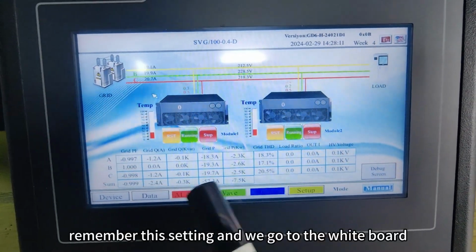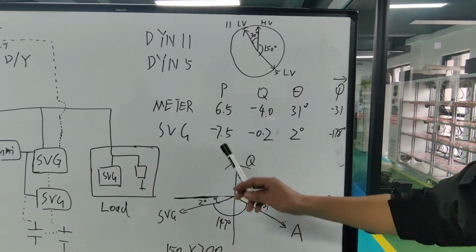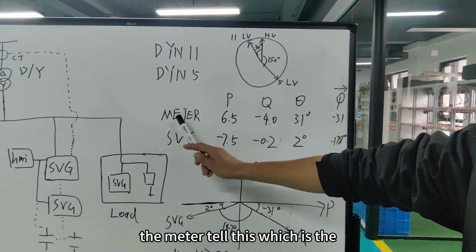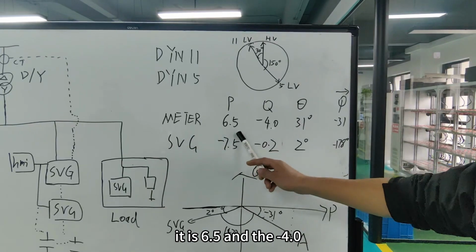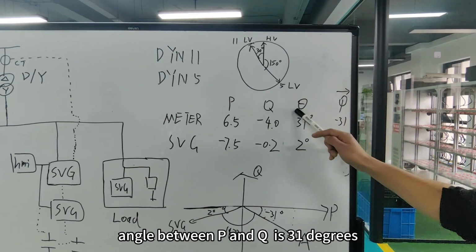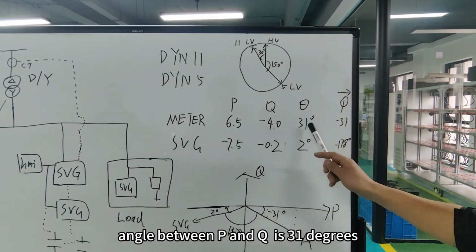So the only thing we need to do is set the phase. Okay, we remember the setting and go to the whiteboard. On the whiteboard, the data we just read from the meter, which is the real value, is 5.5 active and capacitive 4. The angle between P and Q is 31 degrees.